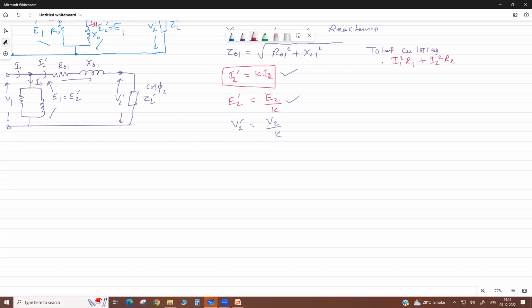Okay, dear. Primary copper loss plus secondary copper loss. Now, as referred to primary side, if we take a total resistance R01, then primary side current is I1 square only. See here, actually I0 we neglect, so here I1 equals to I2 dash. Okay. Here it is I1. This is the total resistance. What is the loss here? I1 square R01. This is the total.